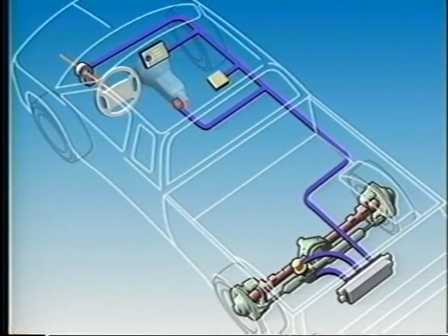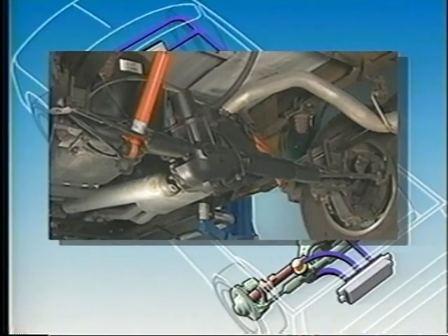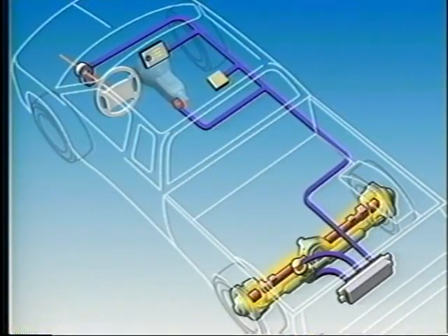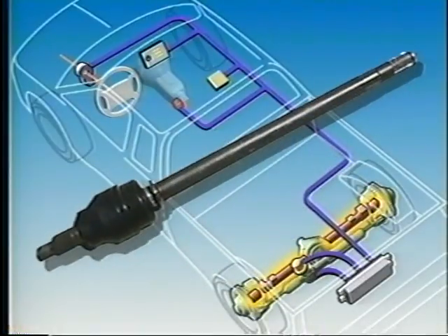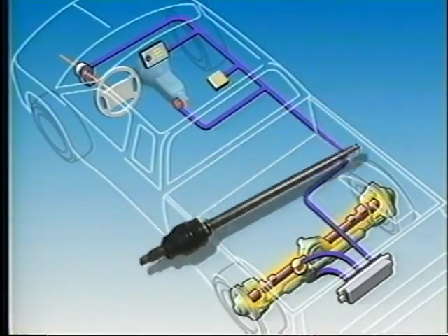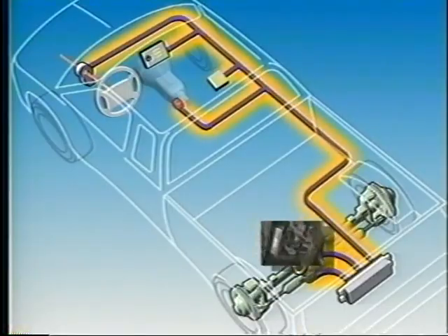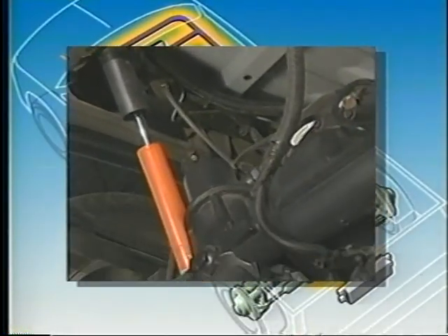The steerable rear axle is located in the same location as a non-steerable rear axle, at the rear of the driveline. The difference, however, is the steerable rear axle includes quarter shafts with steering components on the ends of the quarter shafts. The rear wheel steering control module is located in the underbody rear over the spare tire. The rear actuator consists of the tie rods, rear position sensor, steering gear motor, and rack and pinion boots, and is located behind and above the steerable rear axle. Finally, the rear wheel steering wiring harness is a subcomponent of the main vehicle harness.